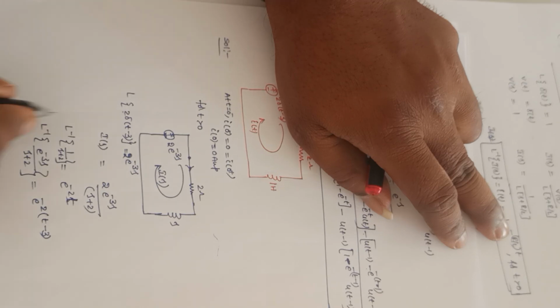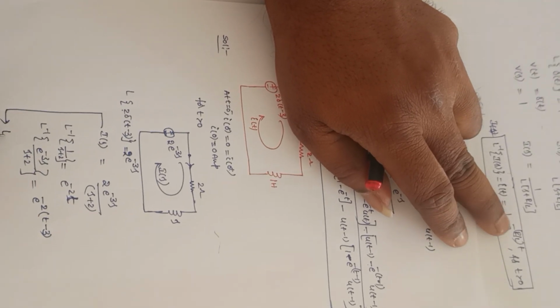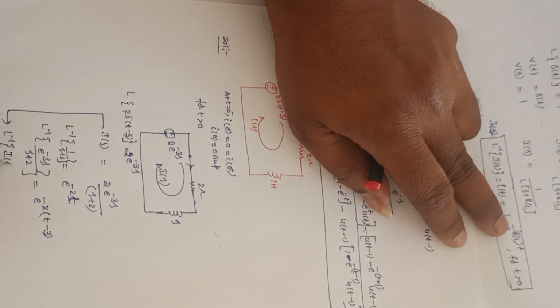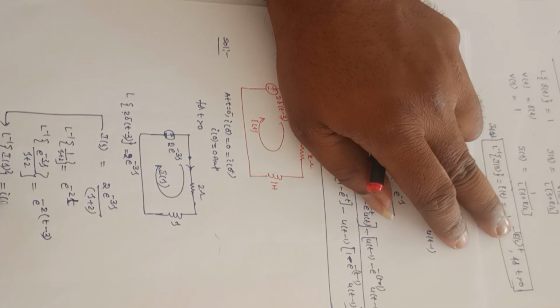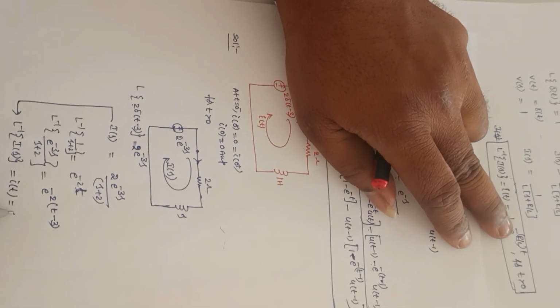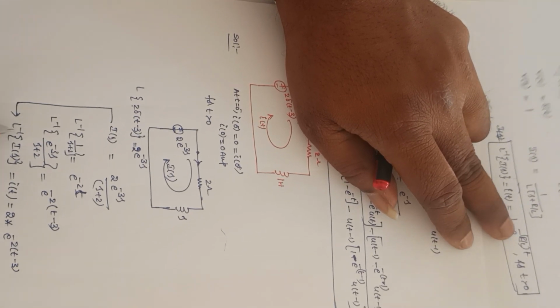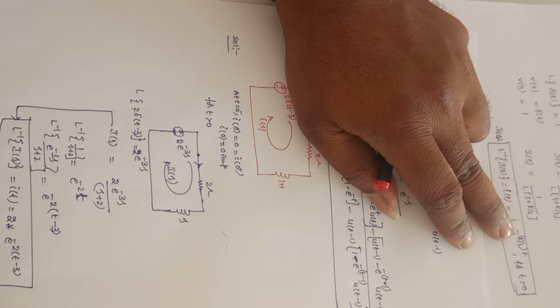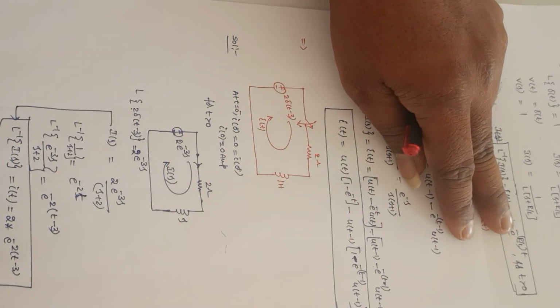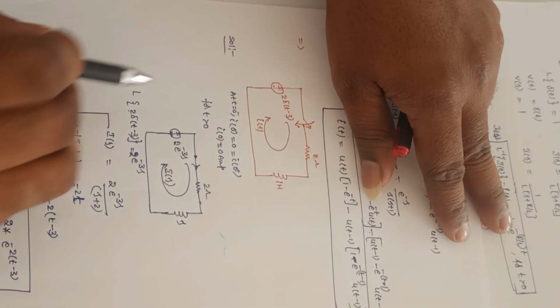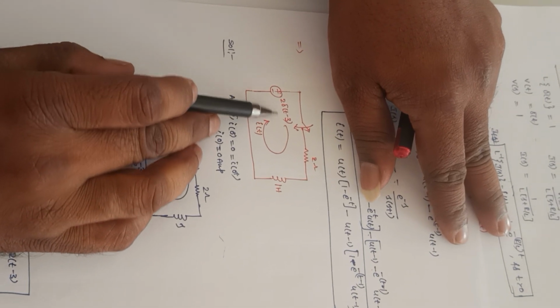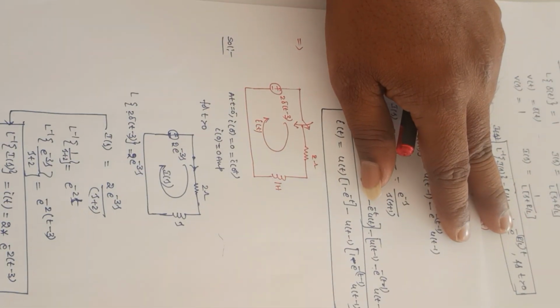So from this, if I apply the inverse Laplace transform for I of s, that is equal to I of t, so it is 2 e power minus 2t minus 3. So this is the response for this RL circuit if we give the excitation as this function.